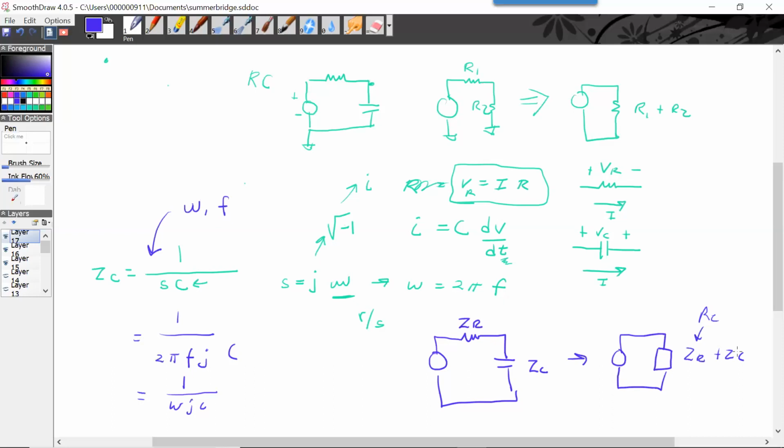So a lot of times in electrical engineering, we kind of bypass the calculus and go straight to the frequency domain, all right? And that means we can do all the same algebra that you learned with resistor manipulation. Same thing for combining resistors in parallel, all right?